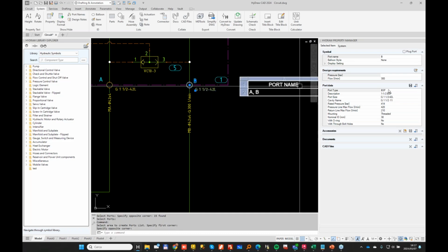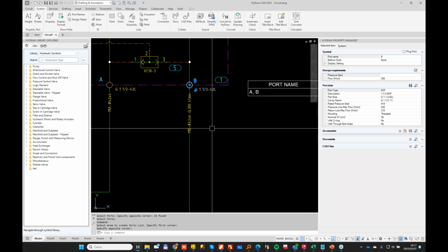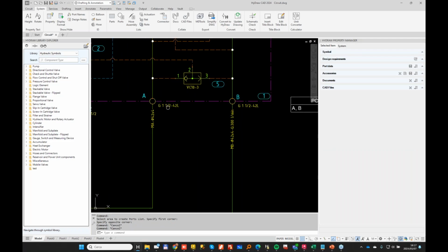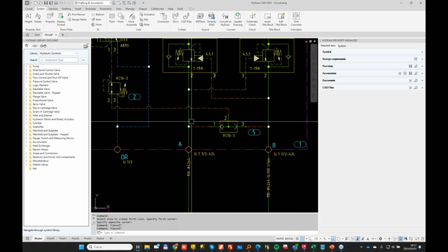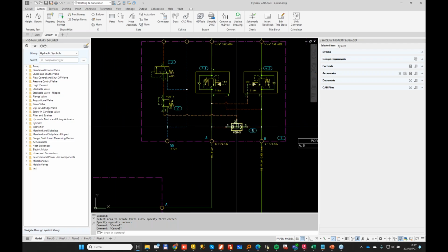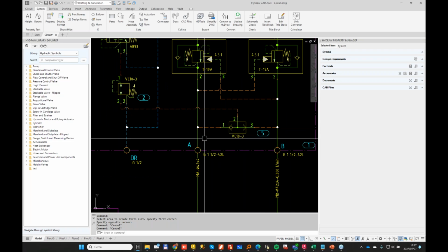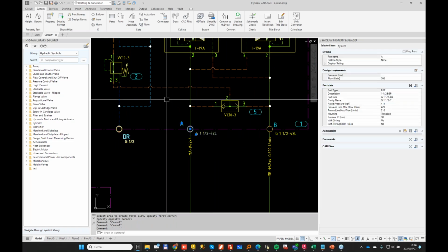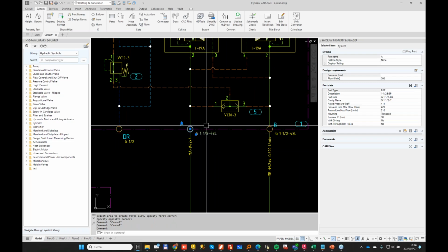Please remember, it is possible to create custom attributes for the ports. So here you could also add the part number for the fitting. I would suggest this technique in case you are defining a system, you are not really taking care about purchasing the fittings, but you want to communicate with your supplier what are the sizes that you need for your system. So if this is the case, like a couple of customers I recently supported, this is a good technique to provide additional information in the diagram that will help the fitting selection.